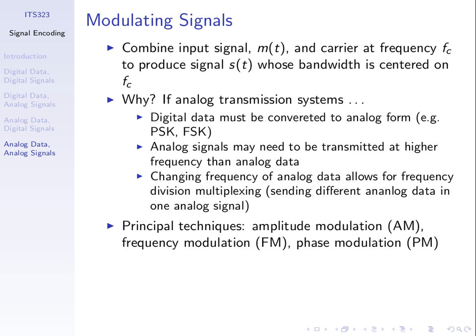With AM radio, or even FM radio, what's a typical frequency? FM 105 what? 105.5 megahertz. So let's say FM radio 105 megahertz. That means the signal is transmitted at a frequency centered around 105 megahertz. The signal, because it has a range of frequency components, is plus or minus a few, probably about 20 kilohertz. So this is the signal that we need to send with FM radio. This is the input, someone talking. So we need to shift this from the 0 to 4,000 hertz up to a frequency of around 105 megahertz.